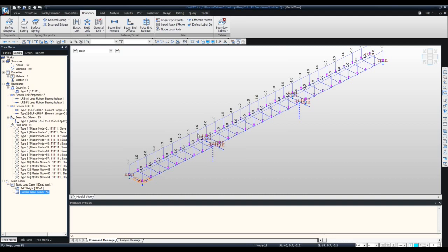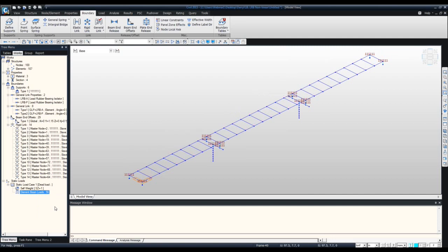Now for seismic analysis, in order for these loads to be taken into account, you have to model them as masses. For seismic analysis, there are three main things that are taken into account: stiffness, damping, and mass. Stiffness and damping I've already defined, but mass still needs to be defined, particularly for these loads. So let me undisplay these now. To undisplay it, just select it and right-click, and these options let you display or undisplay it as you see fit.